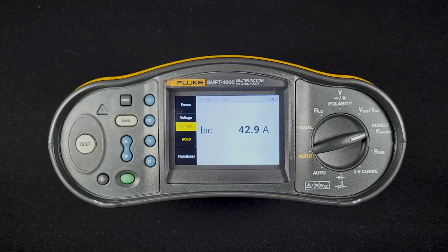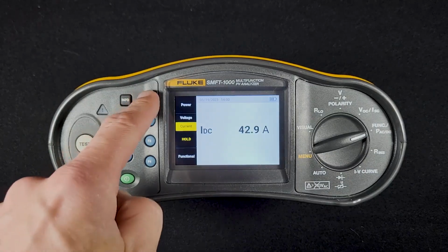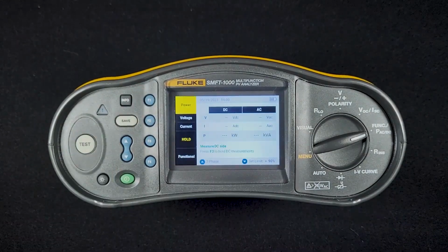I've made that mistake before, so turn the clamp on, go to this current setting and use the dial on the current clamp to zero that clamp out. Obviously, I don't have a current clamp hooked up. It's not zeroed, so I'm getting a false reading here. Then I can go back to power and I can rerun my test using the test button, knowing that I have zeroed out my current clamp. That's important to do before conducting the test.